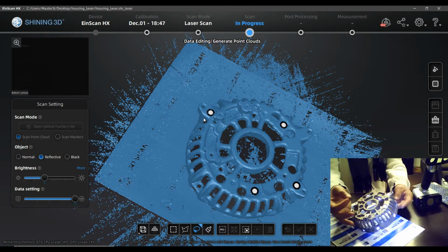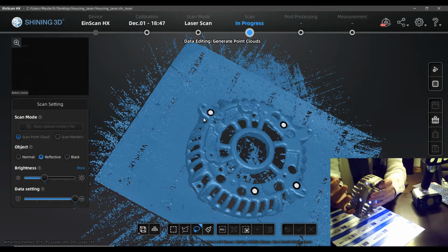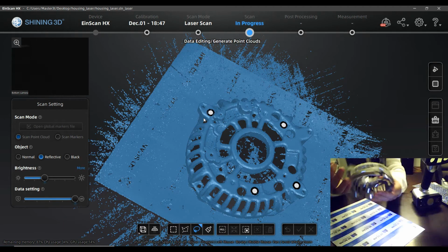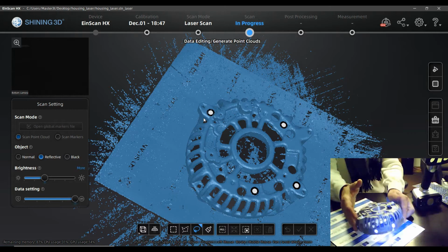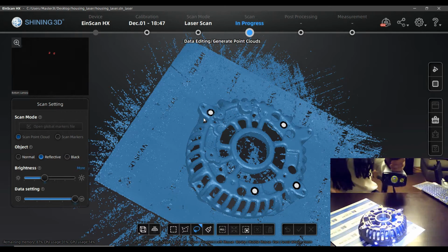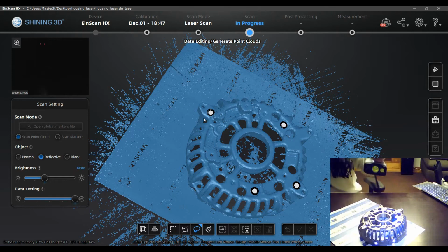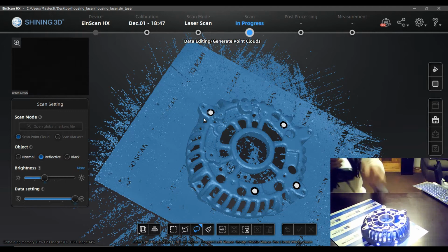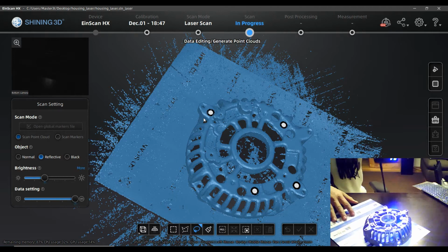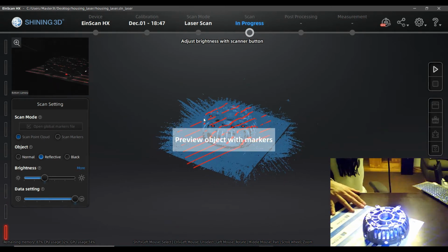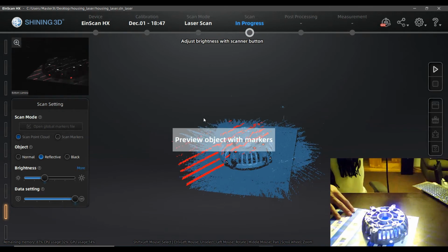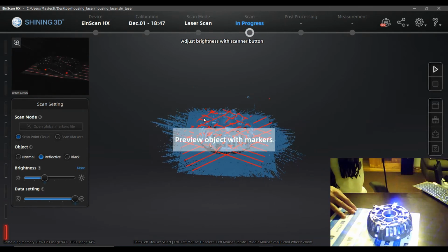So let's see, just around should be better now. I have just a few areas left where there are no markers. Let's stick one here upside, and let's see how it's going to behave. I just didn't start a new scan view again, because it's normally not necessary. I can add markers without a problem, and you will see that he is recognizing the old markers already, and he will use the new markers like he didn't see them before.